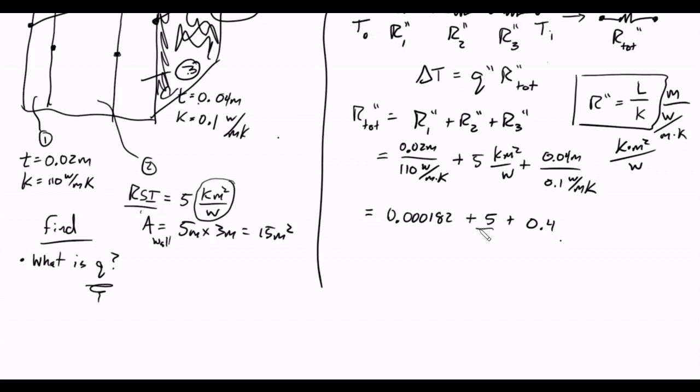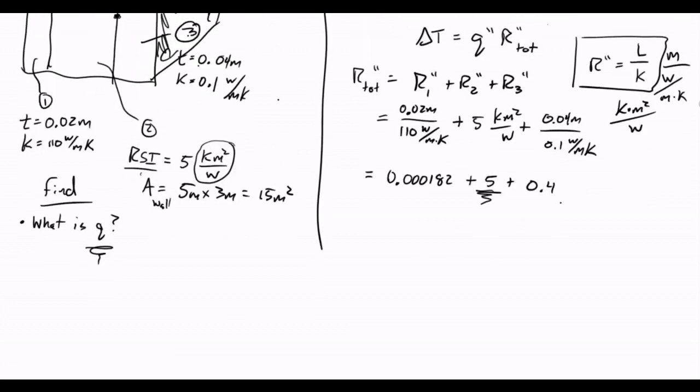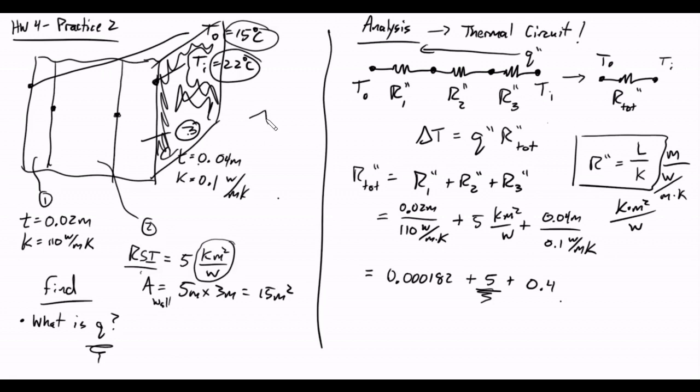So you want a very large R value for your insulation, because the delta T in your home, at least between the inside of your home and the outside of your home, is usually about the same, right? You have a set point in your home, 68 degrees Fahrenheit maybe, and the outside will vary, but depending on how it varies, the more insulation you have, the less heat is allowed to escape.